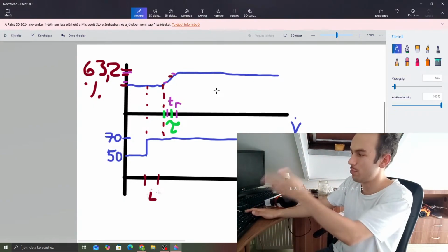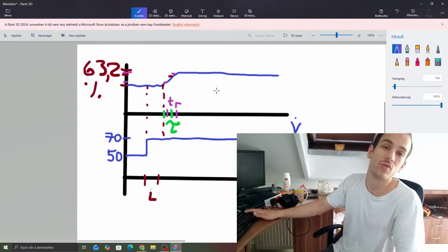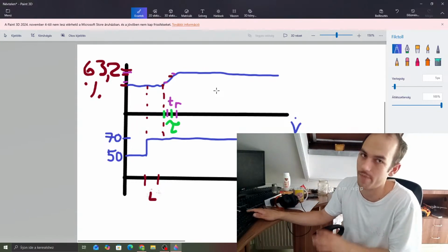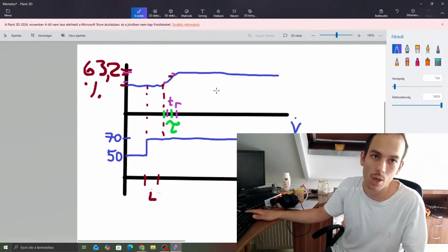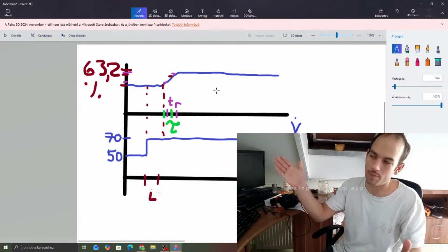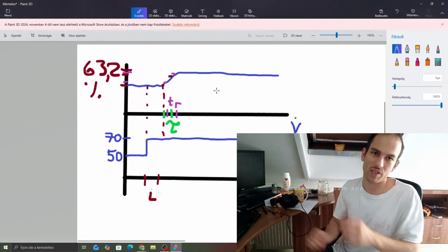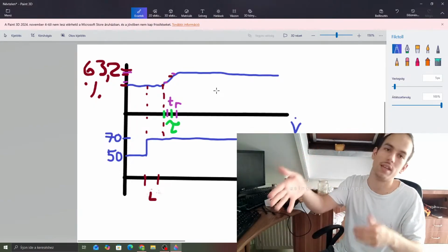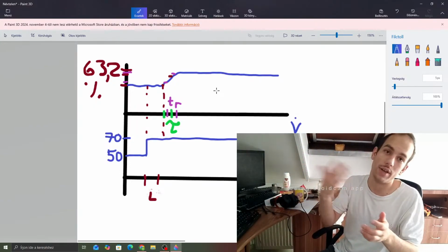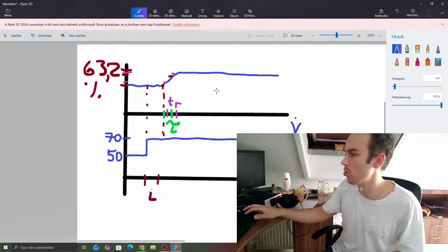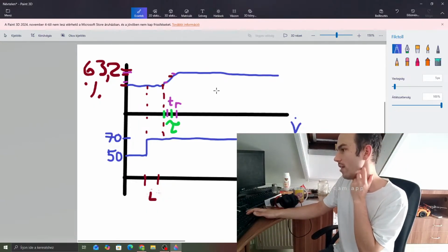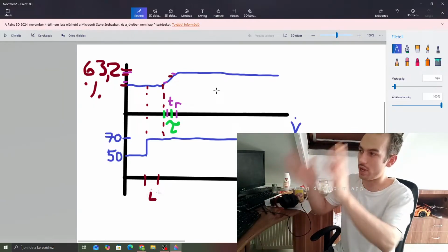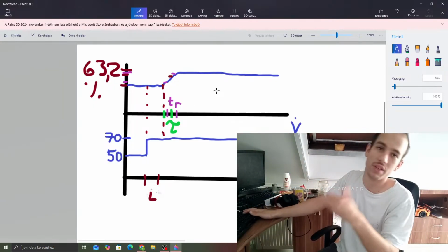Let's say I have this blower going from 50 to 70, or 60 to 70, 65 to 80, 80 to 50. You can also look at the asymmetry, how it reacts going backwards from 80 to 50 rather than 50 to 80. That is also a good thing to look at. Here you can create these little plots and determine these constants.